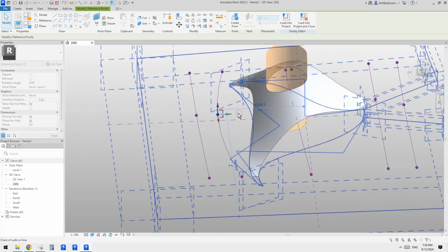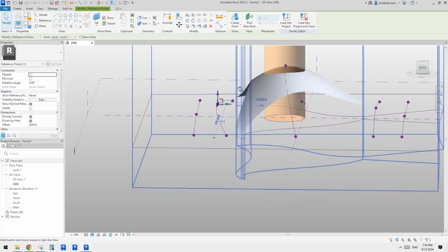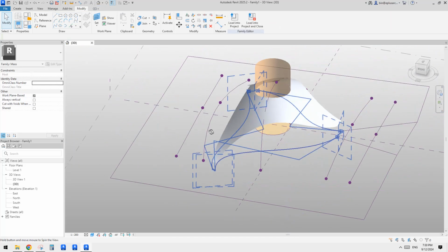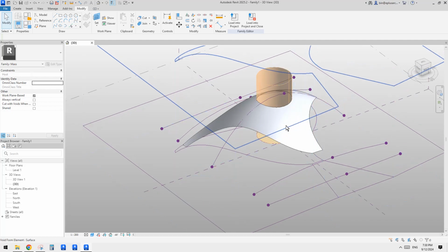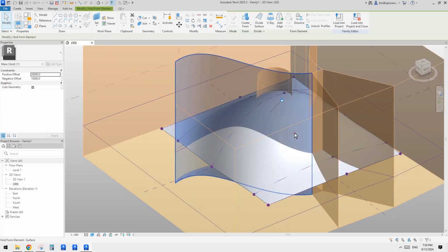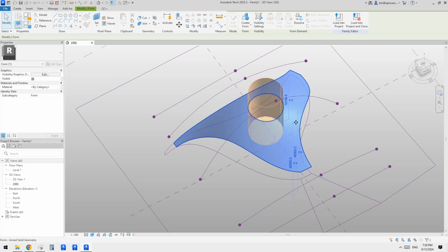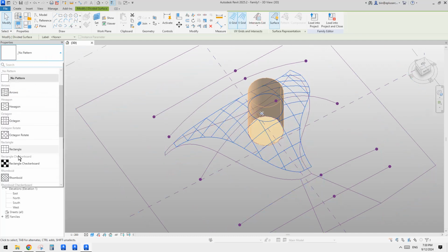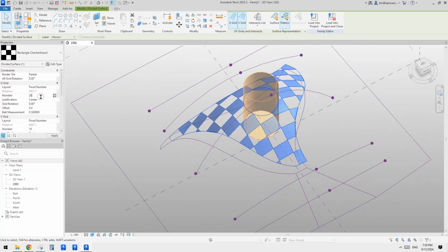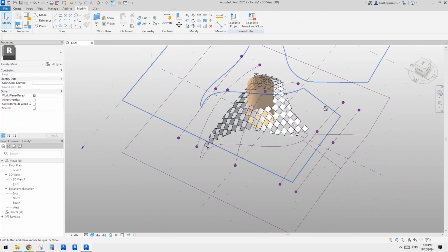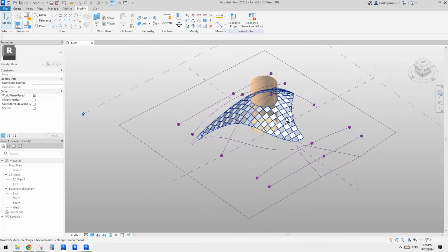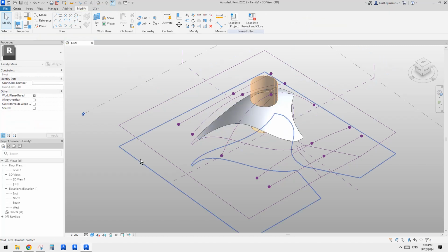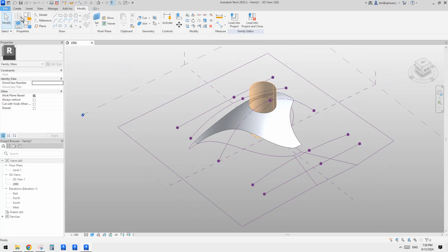So what we can do is, if you want to create something like a pattern, you can directly do it here by selecting this. So it looks like we need to tab twice. Yes, so you can use divided surface and place some, you know, patterns to it. So right, that's this. Or if you only, you know, need a roof, we can just load this one into a project.